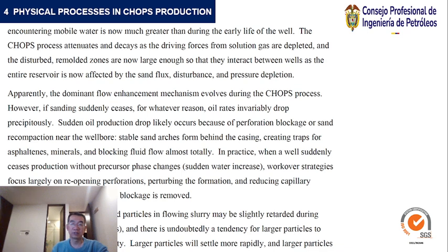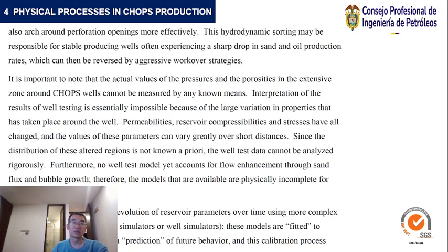Larger particles will settle more rapidly, and larger particles also arch around perforation openings more effectively. This sorting may be responsible for stable producing wells often experiencing a sharp drop in sand and oil producing rates, which can then be resolved by an aggressive workover strategy.